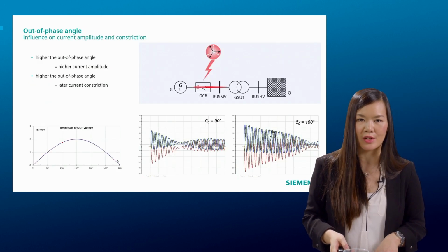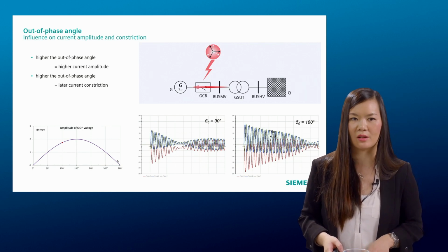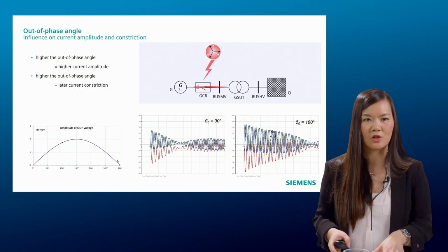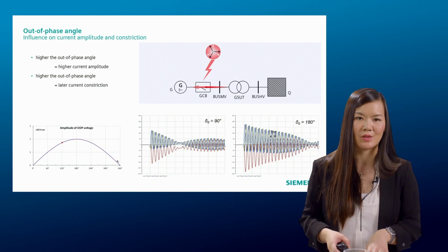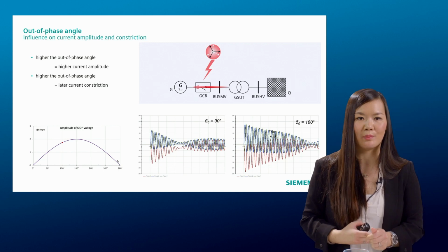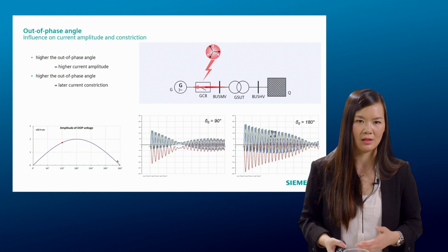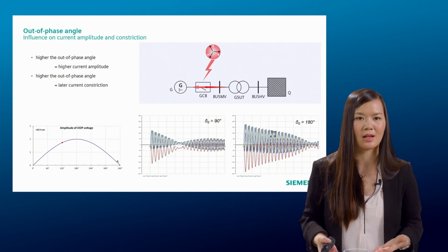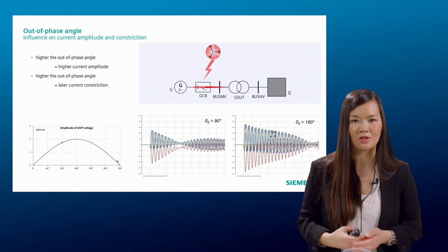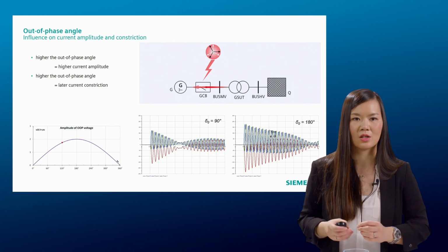Well, we just spoke about the general input and how much the operating points influence the short circuit current behavior. One of the main jobs, as I mentioned before, is the synchronization of the generator and the grid. So what happens to the system if we have a false synchronization? There's a term in the standard called the out of phase switching duty. That means we intentionally test the case where the synchronization is not in phase.